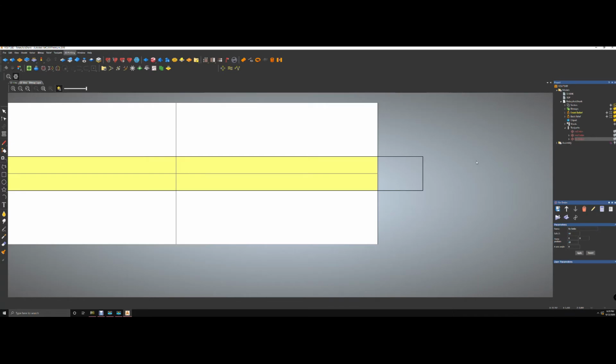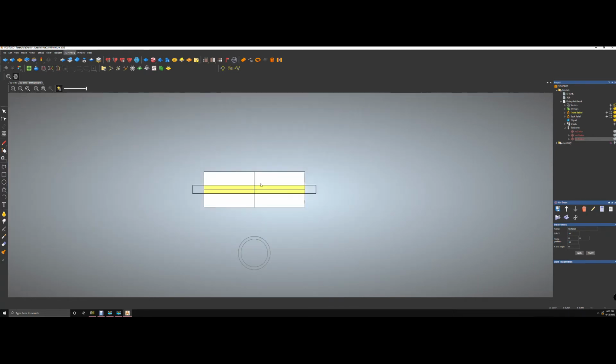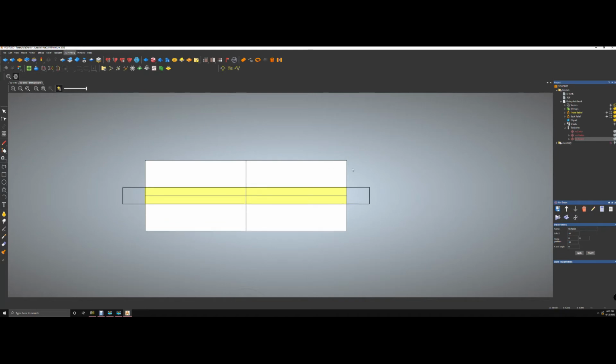But before you do that, it's very important that you don't want this vector to be outside, because we're going to select vector only versus the whole relief. We don't want the mill to be running all these empty spots before it reaches the actual model, because it's going to work its way up and down, up and down. That will take forever. So we want to only mill the actual model.